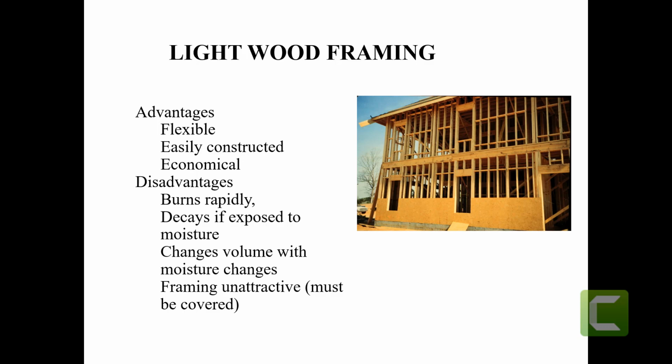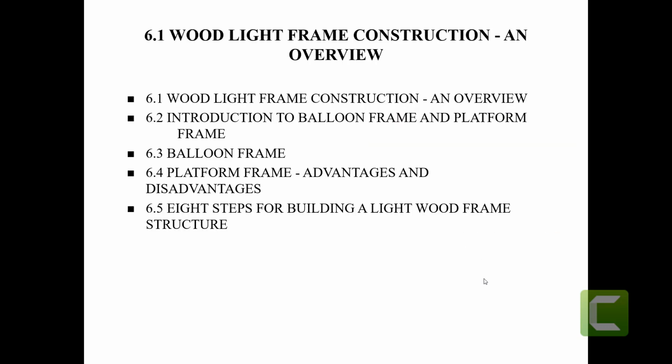Now, it does have its own disadvantages. It can burn rapidly. That has been a problem. It decays, termites, and things of that nature. And framing overall, it is a very tedious process. And since it's so tectonic, you have a lot of parts that come together. So any joint that causes issue can actually lead to problems with wood. Now, we're going to be trying to cover as much about wood as possible when it comes to light frame construction, and then we want to get into how a wall is framed.